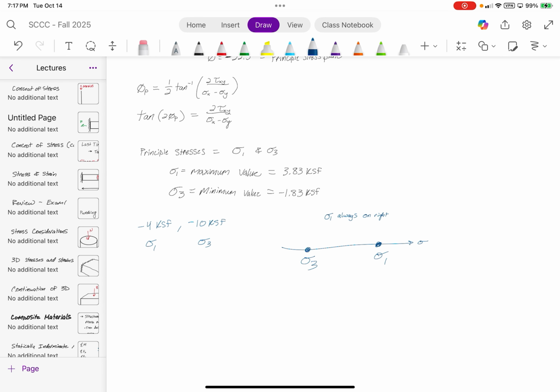And then for the system 1, what you would need to do is compute the deformation due to the applied reaction force. And then you need to add the 2 results together, which, once you start adding temperature into the effect, yeah, it takes a while. So what you're really doing at that point is solving 4 problems all in one.